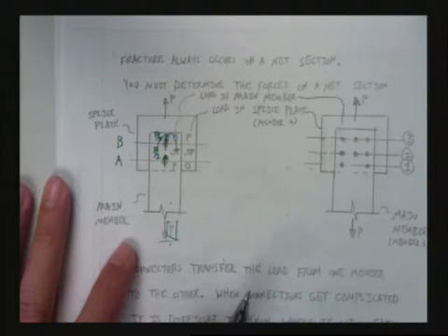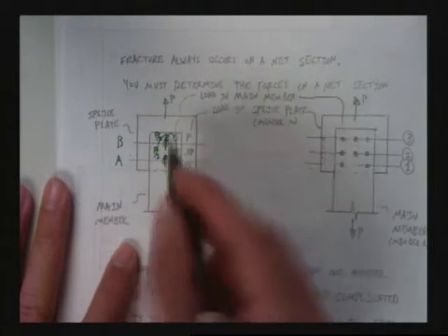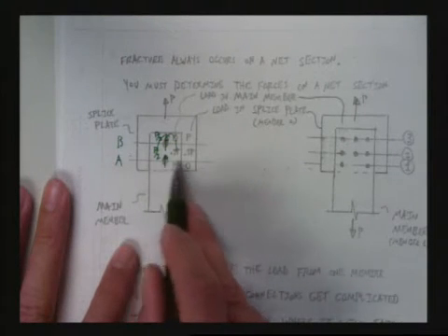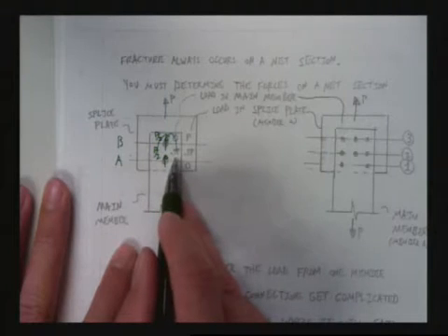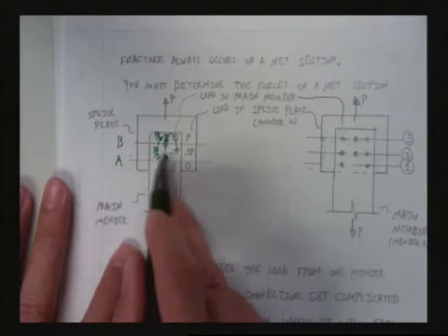Why? Because at B, that front bolt is still taking load, so you don't need that half load. Right. The load in the plate at this line is P. The load in the plate at this line is actually 0.5P, because some of the load has already left.